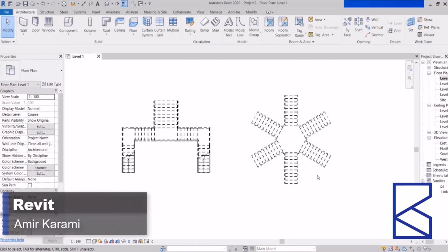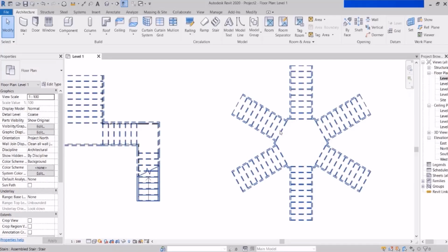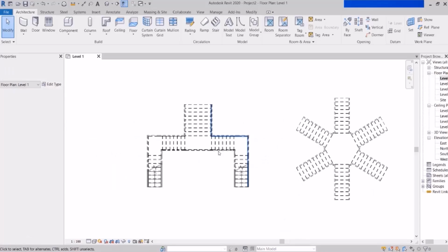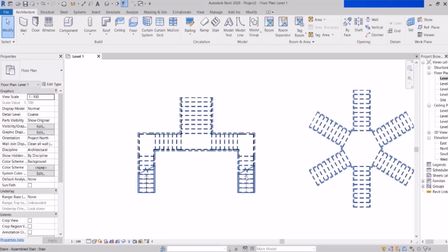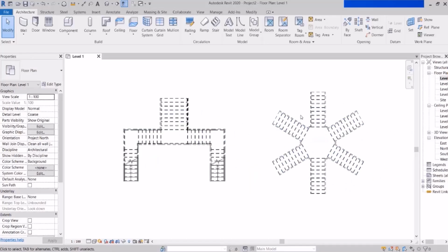Next kind of the stairs is the kind that two or more than two ramps are connected to a single landing. This one has two ramps, but this one, we get to the landing from three ramps and we exit from it from three other ramps. This one, for example, we enter from two ramps and we exit from one ramp. These are usually used in the lobbies more than others.